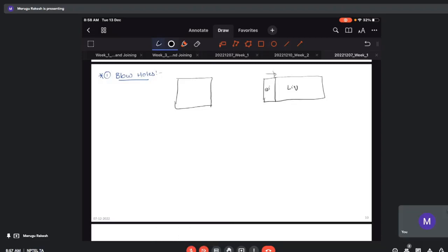Now I'm removing heat from this side, for understanding purposes. So this is the front that is moving. Initially there will be some x% of concentration in the whole liquid. When the solid front is moving further, this solid will reject some of the gas, say hydrogen for example, into the liquid. So each time, the gas concentration in the liquid will increase by some delta x amount.